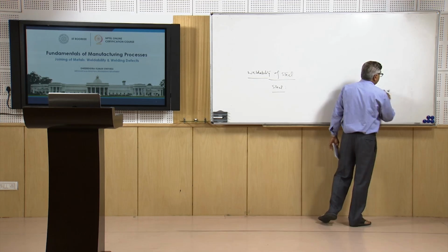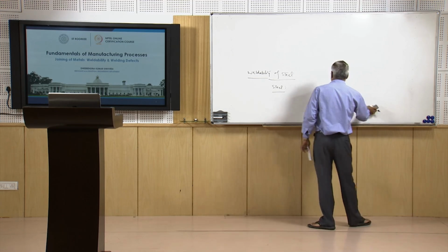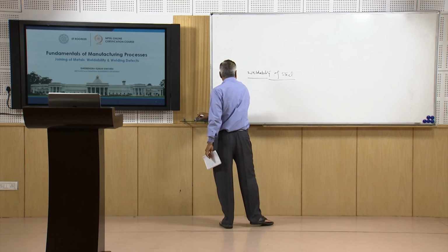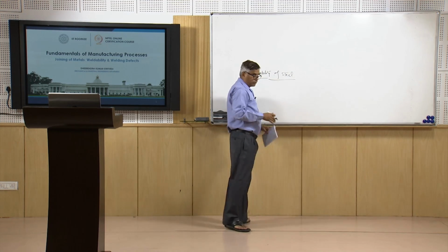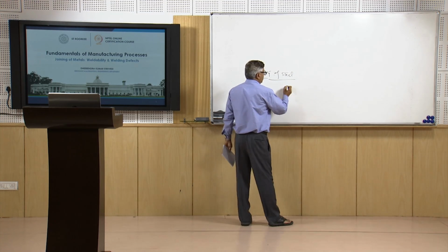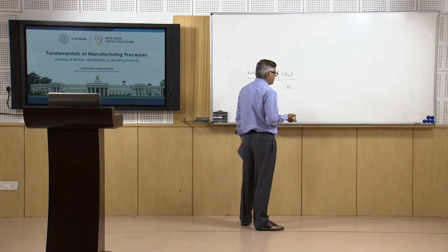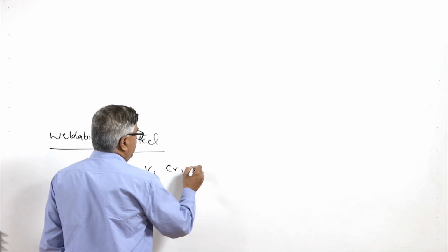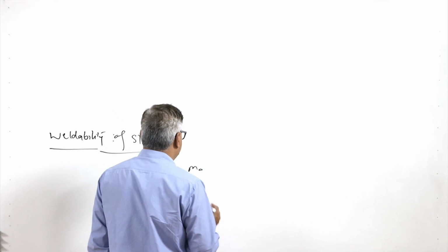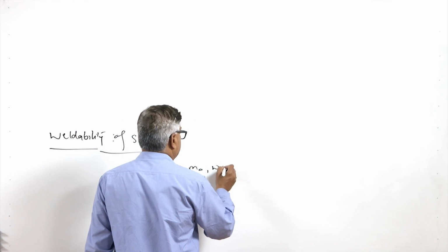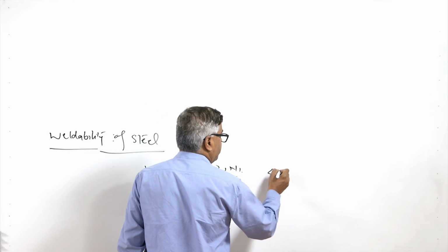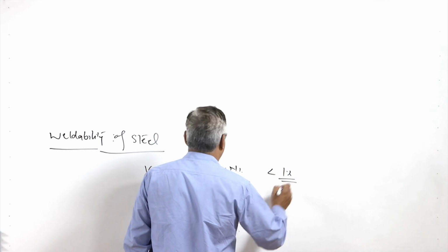That is why carbon is considered the prime alloying element in carbon steels. But sometimes, to achieve a specific set of properties like corrosion resistance, higher strength, improved ductility and toughness, alloying elements like vanadium are added as a refiner, chromium and molybdenum are used as hardening elements because they improve the hardenability, and tungsten, nickel etc. are added in very small amounts, where the weight percentage is less than 1%.